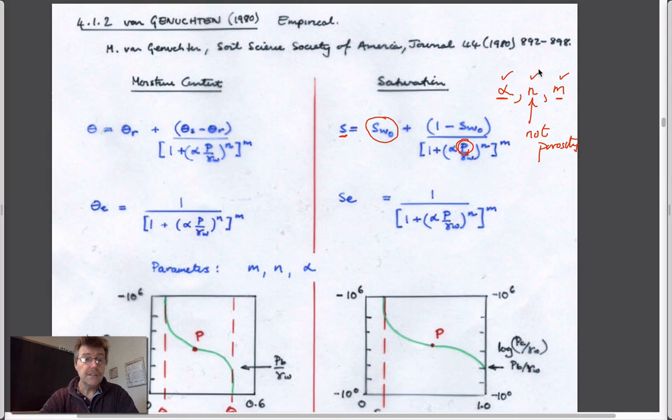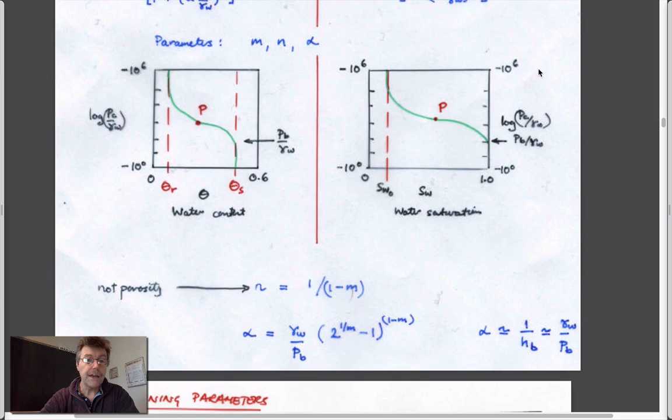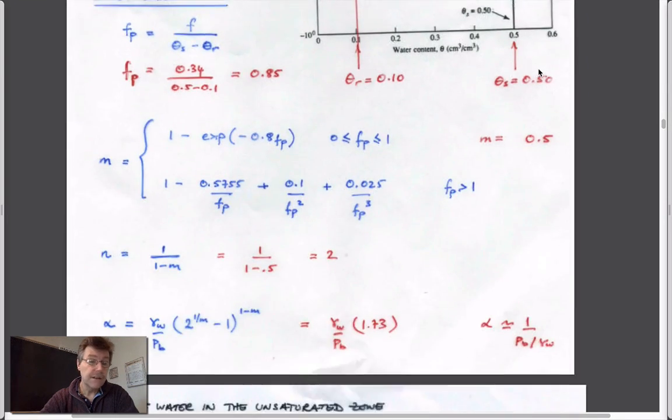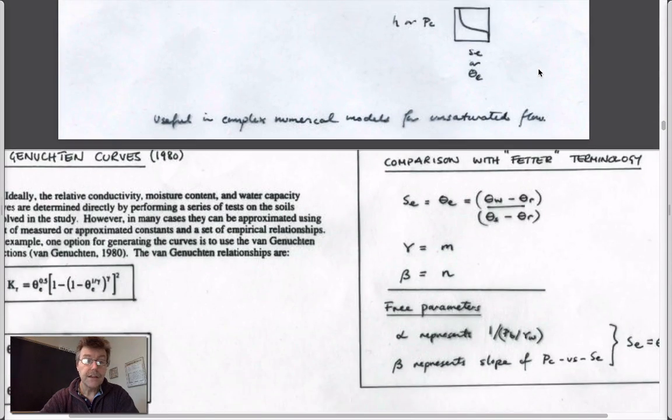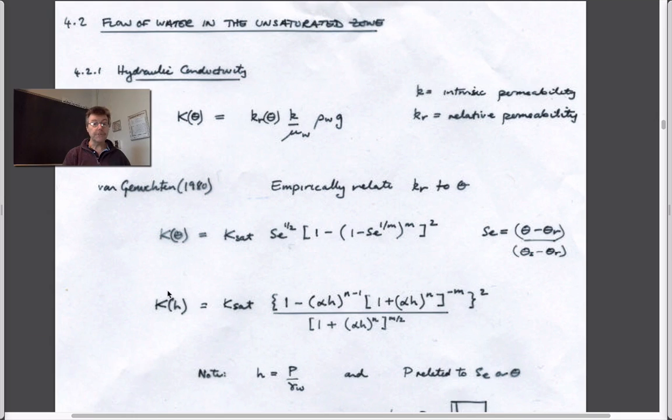And so in addition to the Van Genuchten method giving you a picture of a capillary pressure versus saturation curve and a method to do that, it can also give you a picture of the relative permeability curve, how permeability varies either with saturation or with, well, volumetric moisture content, right? So this is just a proxy for saturation.